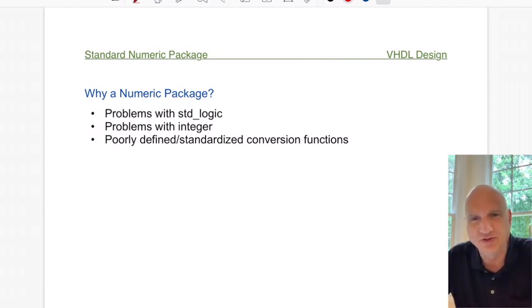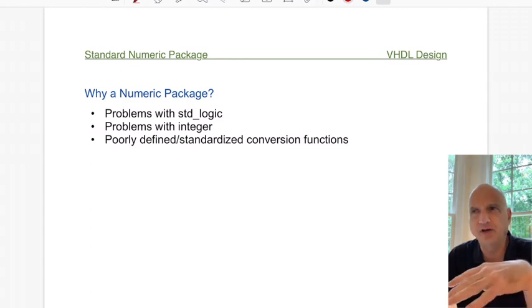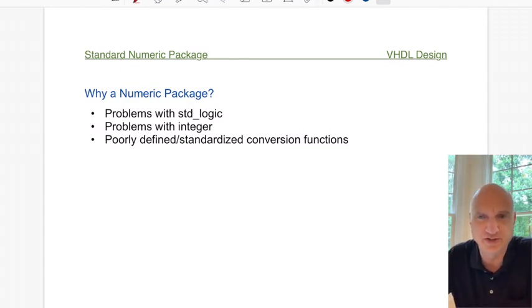And then when you did that, you could access the individual bits of the bus, transfer them to one part of the design or the other, but you really couldn't treat the elements as a value by itself. You couldn't say take an 8-bit standard logic vector, add the value 8 to it, and then hope to get some sort of answer, because standard logic vector isn't about a value, it's a grouping of independent signals. And so adding numbers together made no sense from that standpoint.